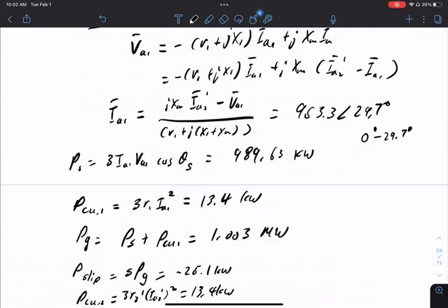That could happen. Normally you can control either active power or reactive power, but you cannot consider everything. So you say, I want reactive power to come out of this, then maybe active power will cycle. You want to avoid cycling too much active power through the circuit, but sometimes it's not avoidable.